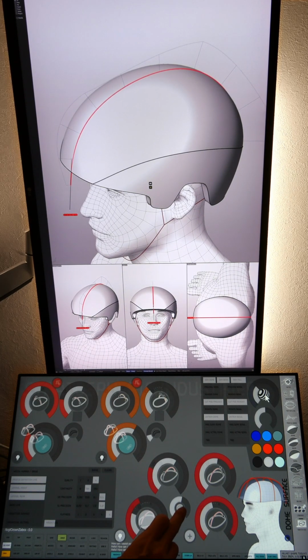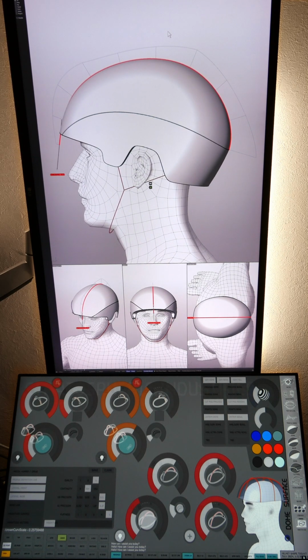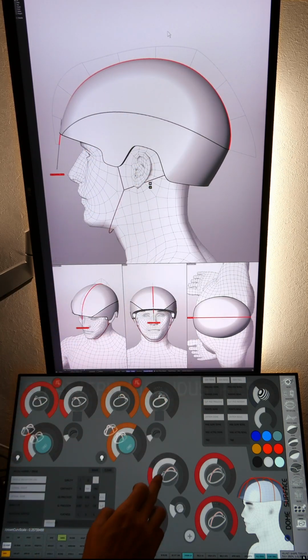Alright, we'll turn off also the comb. Okay, the comb magnitude can be controlled there, as we saw before. That lets you adjust the curvature of the middle of the line. That indicates the magnitude of the curvature. So if you feel like there's a little bit of a flat spot there, you can go through and just give that a little bit of a boost.